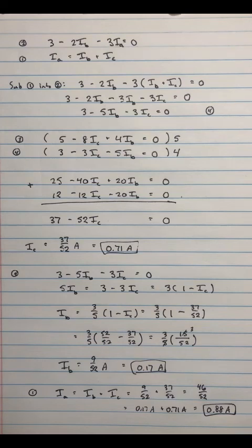So now, again, several things that we found out in doing this particular case. First off, you must start with the physics concepts of conservation of charge and conservation of energy, which in practice are Kirchhoff's rules: the current junction rule and the voltage rule for a loop. You have to use those particular rules. It doesn't help to talk directly about series or parallel resistors so much anymore, because you've got a weird mix of that.